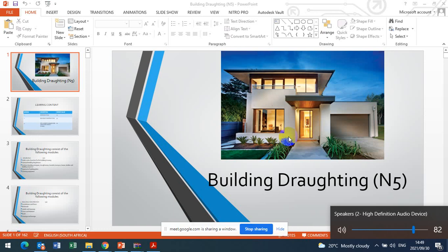That is also another important paper I give students when I'm just starting. And then I tell them that the minimum length of any room is 2 meters. That is according to SANS, South African National Standards. 2 meters is the minimum length except for passage, kitchen, scullery, and the corridors. You can have less; the minimum for a passage is 800, but the standard is 900 for your passage. Use 900 as well.